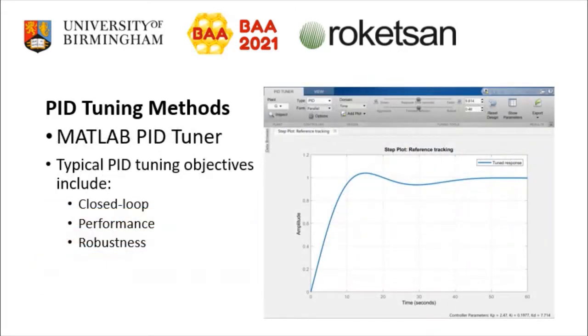Let's evaluate the PID tuner of MATLAB, which is already widely used. It seems pretty compact. You can handle some adjustments and obtain the tuned controller parameters. The adjustments are also related to the objectives of the controller goals, such as response time and robustness. This interface uses an optimization-based code in the background, in fact.